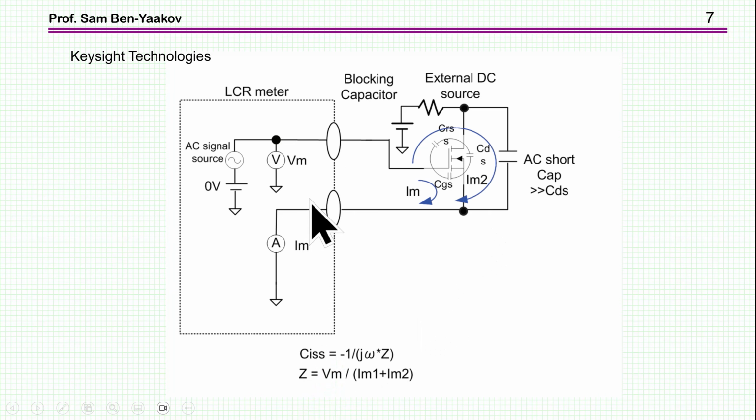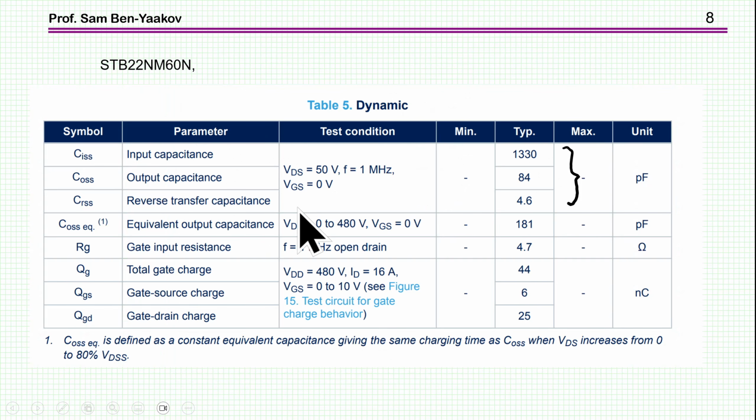And then this voltage will be changing, so we get different points. And then we have here the gate voltage with some small signal excitation, and the current is measured here. So we get the voltage, we get the current, so we can calculate what is the local small signal or differential capacitance.